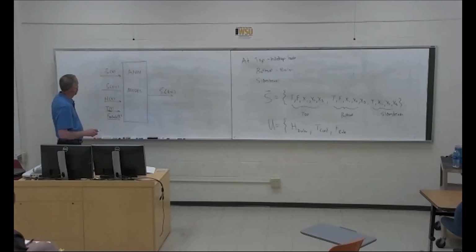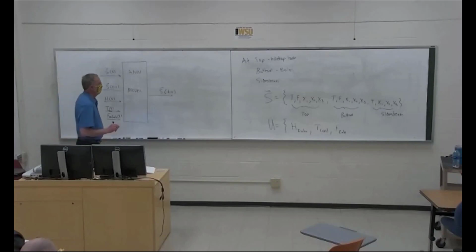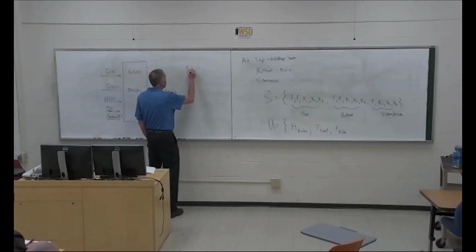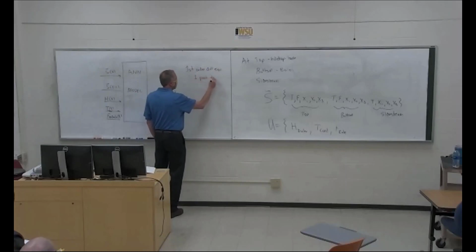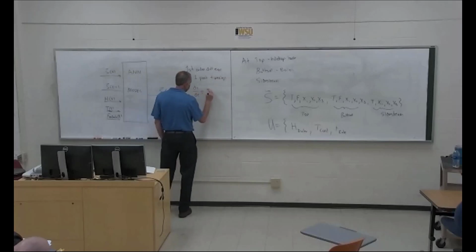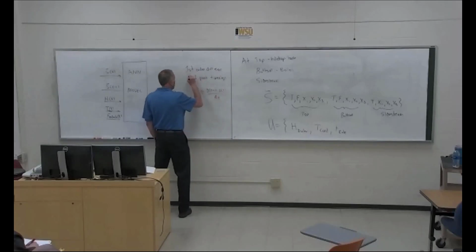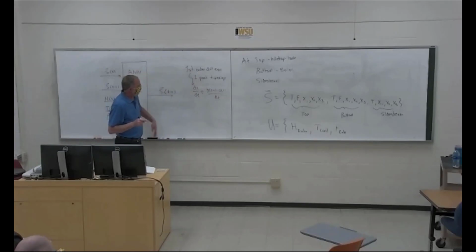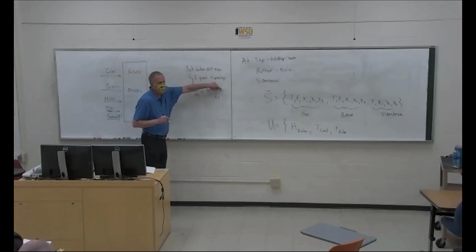So based on when we did system modeling, we found out the first order differential equation needed 1 time step because, like the dy by dt, you approximate that as y at t plus 1 minus y at t over delta t based on first order, which is 1 derivative. And so you can predict the next time step based on the current time step plus whatever inputs are coming into the system.